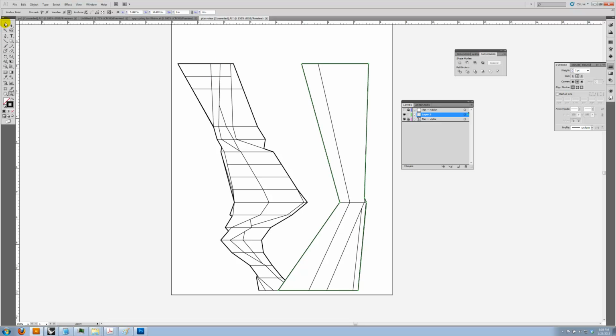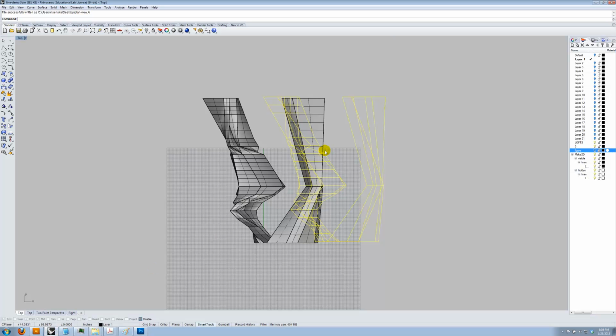Okay, and we've got those, and that may be just fine. I might even go in and change the weight slightly so it's more legible. You want kind of a fine touch with these things, and you also have to think about the lines that you follow on the form. Let's go ahead and actually delete. Actually, I'm just going to undo Make 2D here. As you're doing this process, it's a good idea to just undo Make 2D. That way it doesn't create all those layers. You don't have to worry about it.